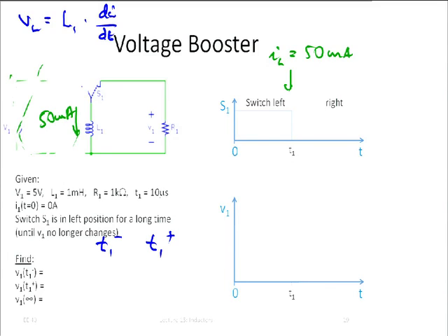And just when I flip the switch now, so actually it's not 50, but almost. So how do we figure that out? Where is that current flowing? What's the current flowing through the resistor? 50 milliamps. Now we have Ohm's law, 50 milliamps times 1 kΩ. It's 50 volts, right? So this voltage here is 50 volts. Okay, and so the voltage is actually minus 50 volts.